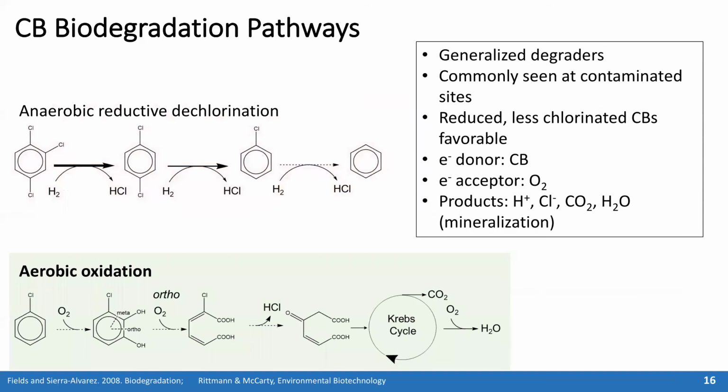And then we know that chlorinated benzenes can also degrade aerobically, particularly the ones that have fewer chlorines on them. So here in the lower frame, you see chlorinated benzene. It can react with an organism that's aerobic, with oxygen, and it cleaves it, and then you break apart the ring, and you get complete mineralization of the compound. So basically, we completely detoxify the chlorinated benzene this way.